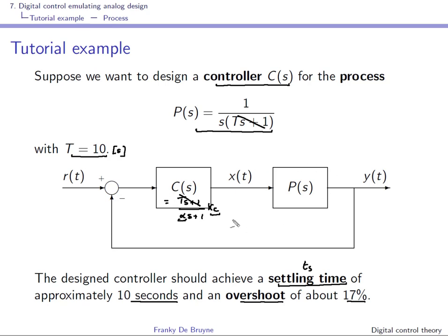We will see in next year's course, Practical Process Control, that this is not necessarily a good strategy in the presence of a load disturbance, w(t), or as we sometimes write it, d_L, because the zero in the controller will prevent you from efficiently rejecting this load disturbance.